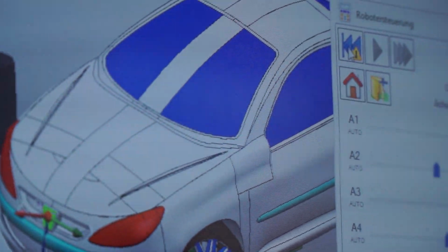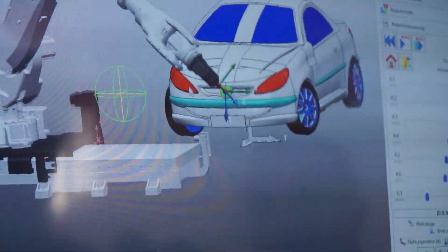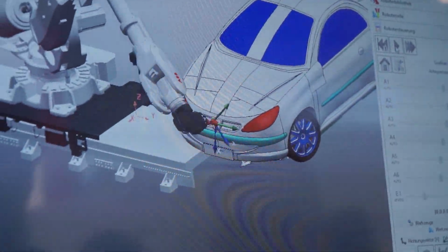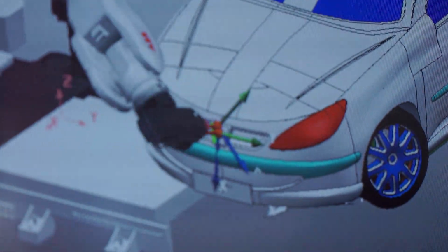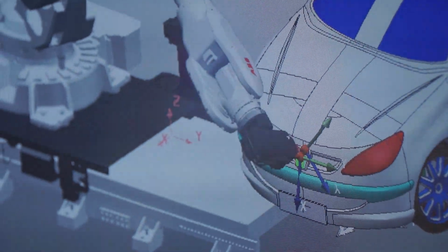So we're going to position the robot in this situation. Can we then still machine that? Then it's going to try that with the new position of the robot. And let's have a look. Well, to be honest, this looks better. I like that more. The robot is a bit further away, the chances for collisions are less.